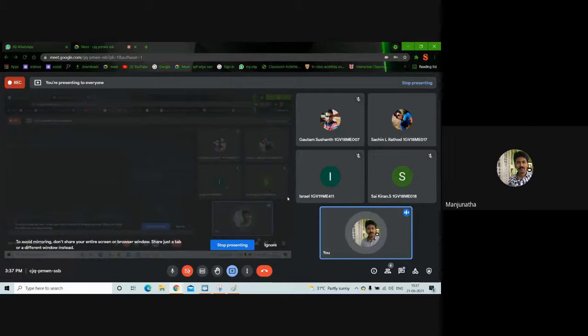So nothing. What you have to do, you have to drag a box, and you just click on okay. Then automatically you need to apply that value. You have to define those values for uniformly distributed load. At node A and node 3, you define it as 30. Got it? So automatically it will be applied as a uniformly distributed load on it, and then go to solve. If the solution is done, then it indicates it doesn't have any error.